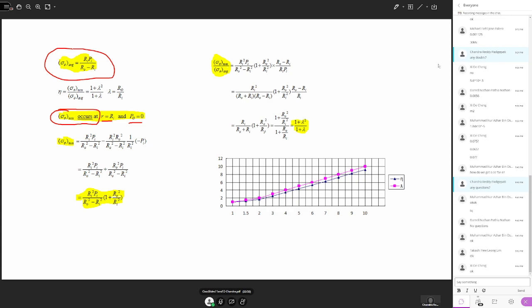So from the formula we replace R squared with Ri squared, and we replace P naught with 0, therefore it becomes negative Pi. When you simplify, you can write it in this form. We're just rearranging the terms. You can cancel out Ri and Ri, then rewrite the resulting equation in this format. That is sigma theta maximum.